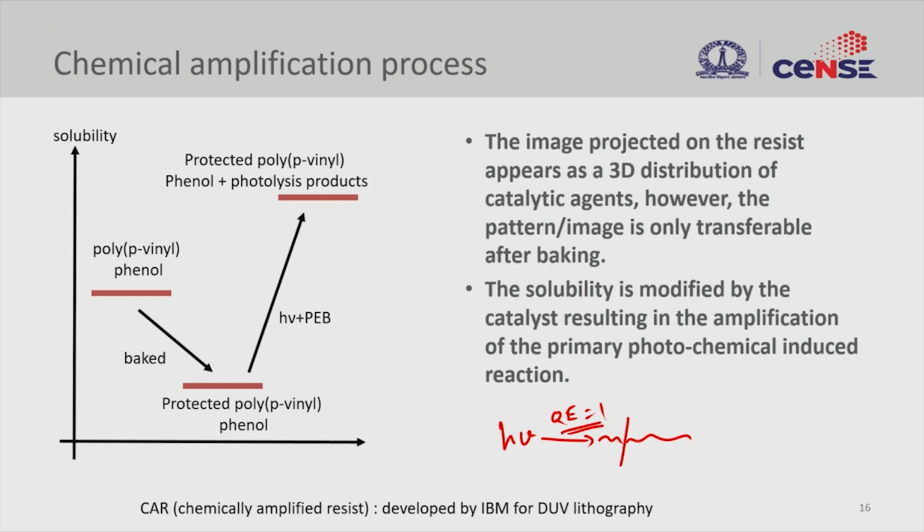So in order to have this process simplified, people use chemical amplification, right? So when you have a very low number of photons, how do you achieve enough chain breakage? People thought about this and they came up with this chemical amplification process. So chemical amplification is nothing but one photon will generate multiple delinking, right? And that happens using this.